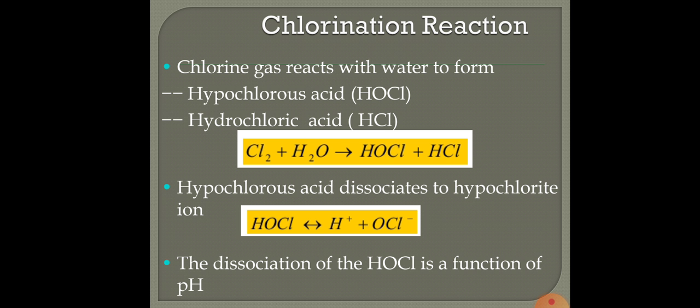So when chlorine is added to water, all three, that is elemental chlorine, hypochlorous acid, and hypochlorite ions, will be formed, and they will remain in equilibrium at different concentrations depending upon the pH of the water. It is actually the pH which controls the amount of the dissociation. So the chlorine existing in water as hypochlorous acid, hypochlorite ions, and molecular chlorine is defined as free available chlorine.